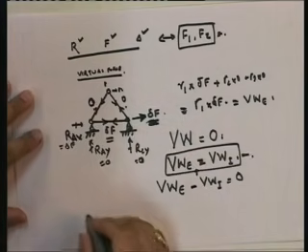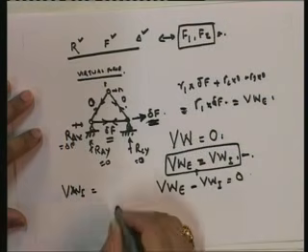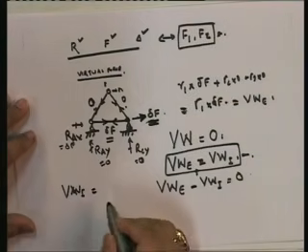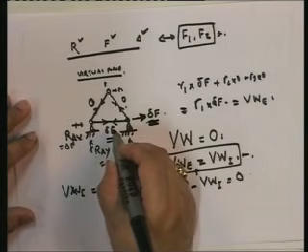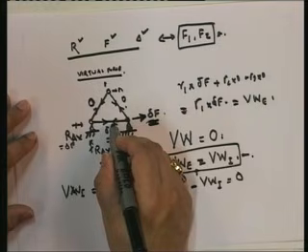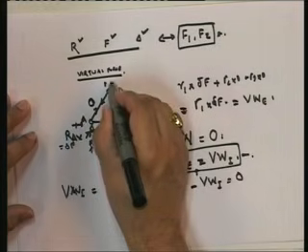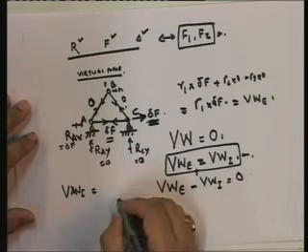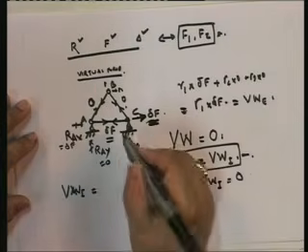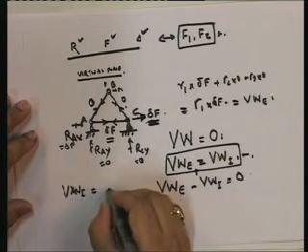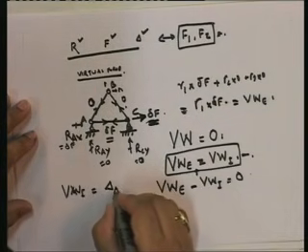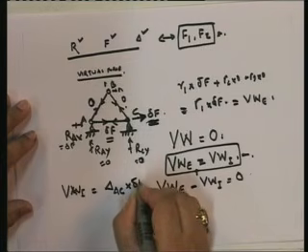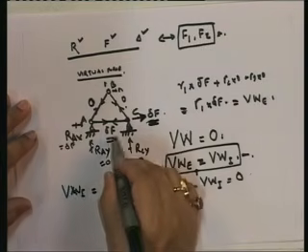In this particular case, the internal virtual work is going to be equal to the virtual force in each member. In member AC, in this structure A, B, C, it's delta F. And what is the real deformation? Delta AC, which we have computed earlier, multiplied by delta F. That's the work done.